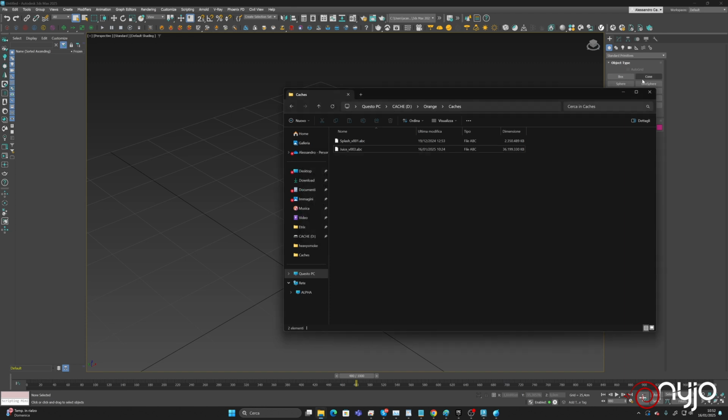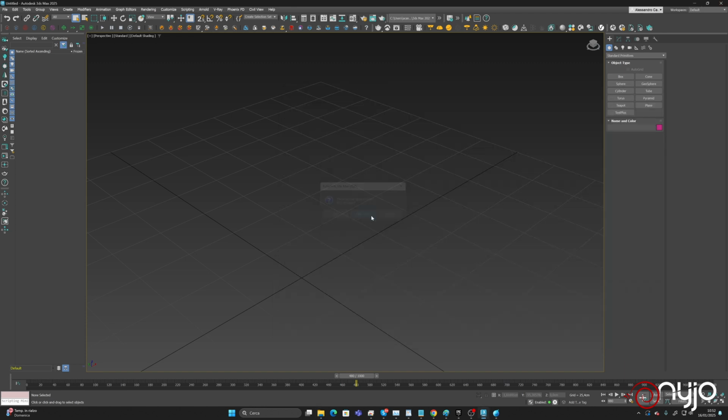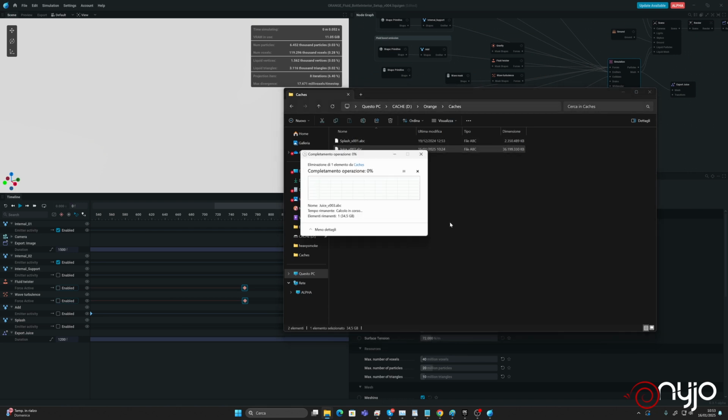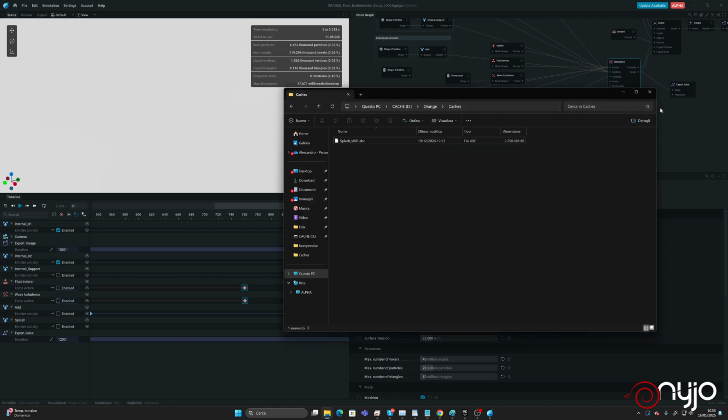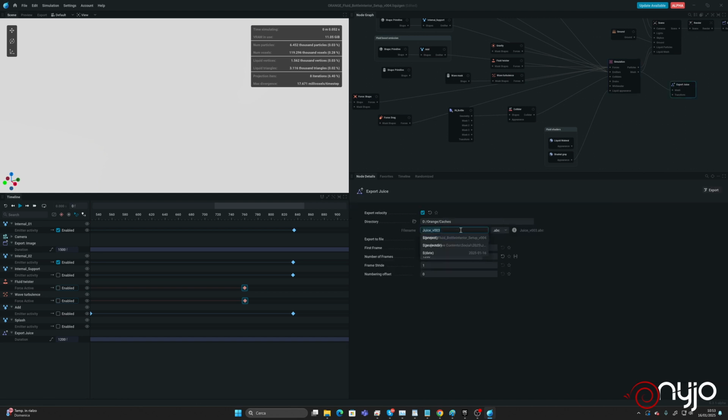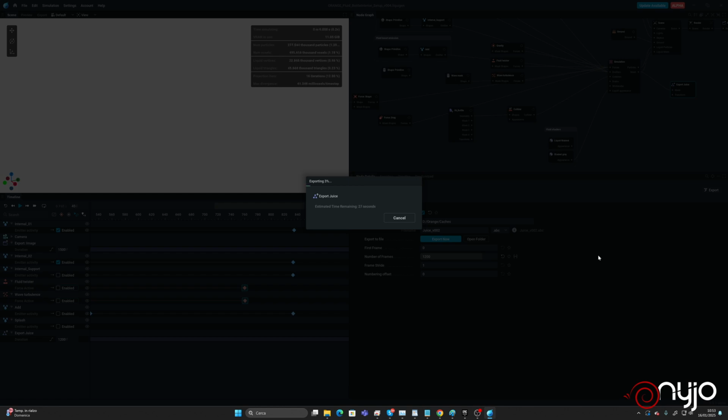By the way, this one is used by 3ds Max, so the best way is to remove 3ds Max and remove this one. Okay, so now we can simulate again with the right resolution and export the GUIs with the number 2 again, because we have no more stuff saved over the cache folder, and export.